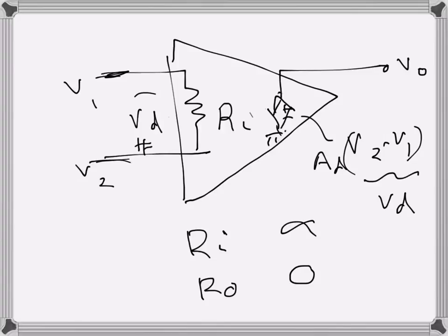Like often we use a voltage source as an ideal voltage source like that. So these are the ideal values, and the voltage gain is infinite, but of course it is limited by the value of the bias voltage. The bias voltage for the 741 is 15 volts, but for different op amps it ranges from 5 to 24 volts. Those details are not important. Depending on the IC, we can use that, but the gain is limited by the saturation voltage.